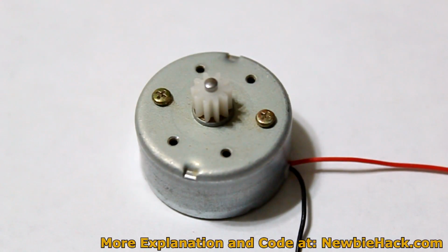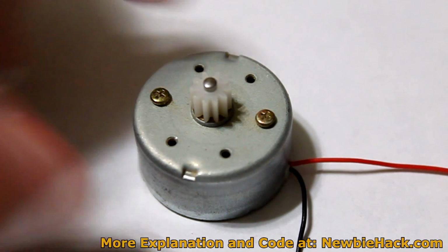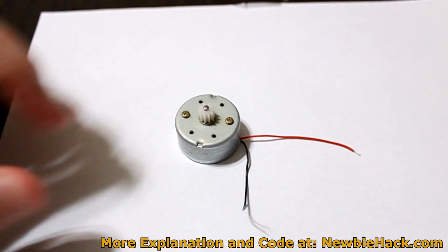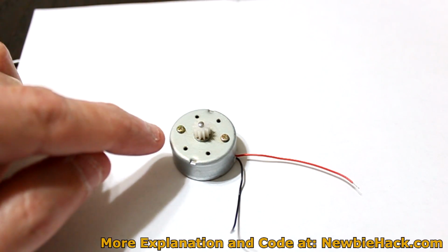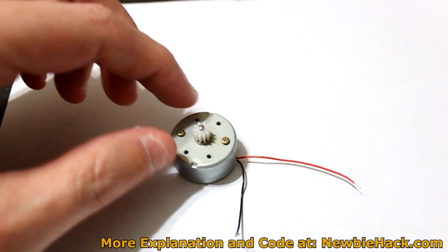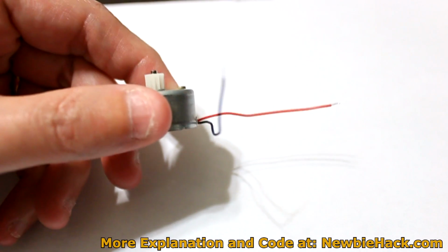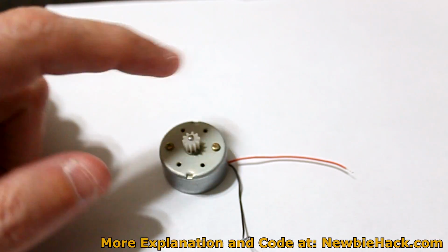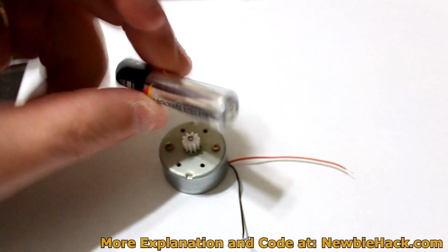Let's use this motor as an example of why we would need PWM output with our microcontrollers. You may already know that if you apply a voltage to a motor, you'll make the motor spin. If you connected this to a microcontroller and you're only able to give it either 0 volts or 5 volts, it would either stop or go at its 5 volt speed. That doesn't really give you much flexibility. You may want the motor to run at different speeds, and you also may want it to run in different directions, clockwise or counterclockwise. So let's see what a motor does when we apply 1.5 volts to it.